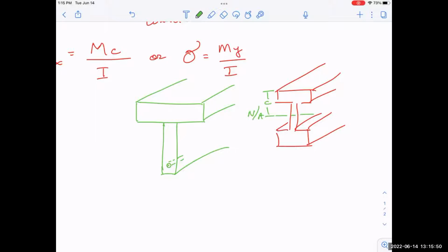If you see them empty going down the road, a flatbed, you'll notice they're not flat. They curve like this. That's because you're going to put weight on it. And wouldn't it be cool if it went to flat so then it behaved normally, instead of you put it on flat and then it's sagging down to the road, so to speak. So they pre-tension it to have camber, expecting that the load will then flatten it out and it'll be easier for forklifts and it'll drive better and so forth.